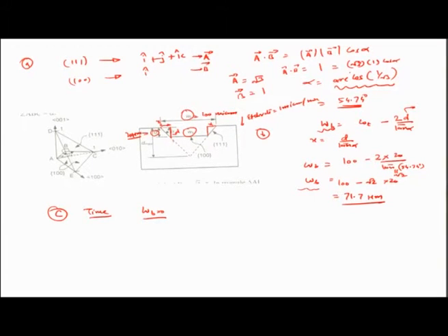So we have projected this 1 1 1 array of walls all the way to the bottom where they meet each other. Assuming that these are the planes corresponding to the slowest or almost negligible etches, when they meet together there is no further etching because there is no material available in the non 1 1 1 plane direction.